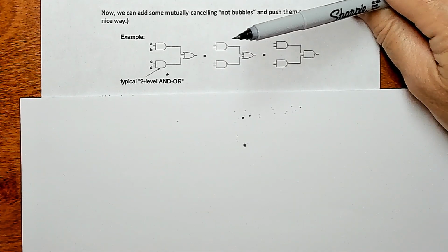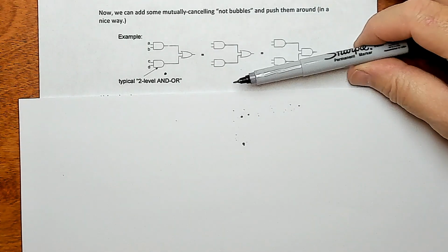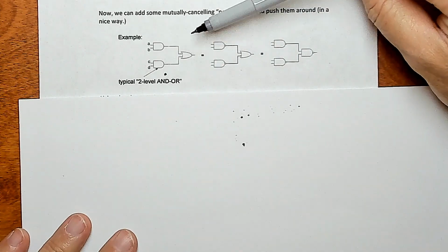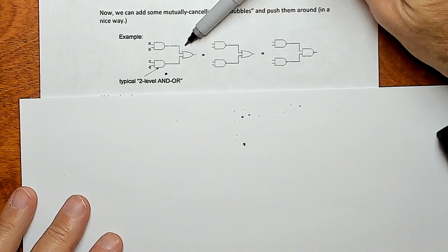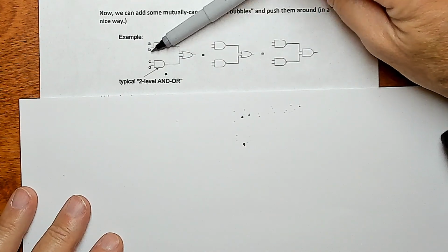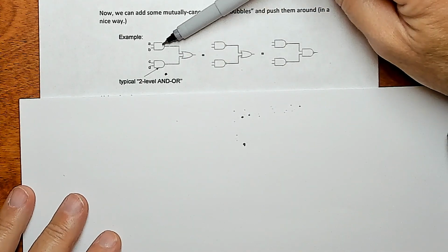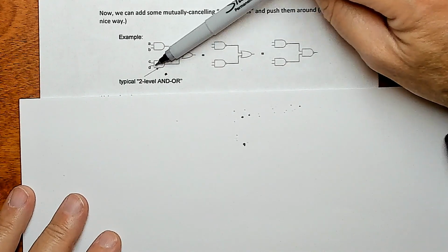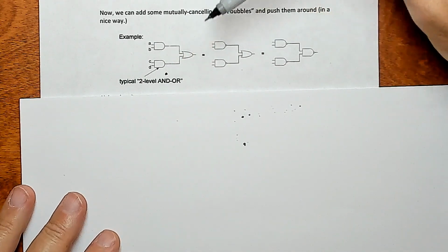The other little trick that we can do, we're working towards proving all you need is NAND. But before we get there, we have to look at this other little trick. So consider the following, if you will. Consider this arbitrary collection of ANDs and ORs. It's a 2-level AND OR thing. You're taking A and B and putting them in an AND gate, and you're taking C, D and putting them in an AND gate, and you're taking that result and putting it in an OR gate.